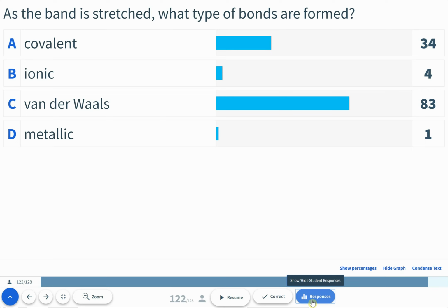So the thing that's resisting me pulling it right now is those cross-links. And I've lined up a bunch of polymer chains. They were like spaghetti, but if I pull on that thing, on average, they start to line up with one another. I know we're just out of time. They start to line up with each other. But as they do, they form van der Waals bonds between the strands of spaghetti.